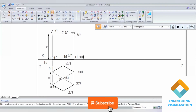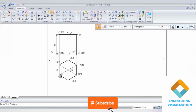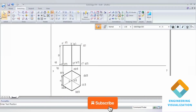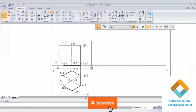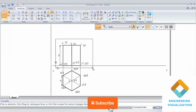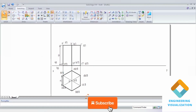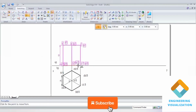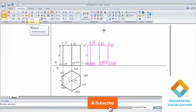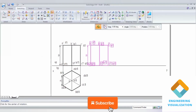Now we need to copy the same diagram using the move command, and we need to incline it with the base edge. The inclination to the base edge is given. Actually they give the angle of inclination to the axis, but we incline with the base edge inclination, which makes the inclination easier. So use the move command, create a copy, slide along the XY line, then go to rotate and take the base edge.